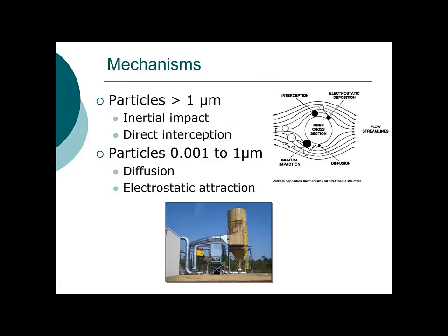When we look at the mechanisms of removal, they range from what is referred to as inertial impact, direct interception, diffusion, and electrostatic attraction. What isn't included in here is also sieving. Sieving means that the particle that you're removing is larger than the pore size.